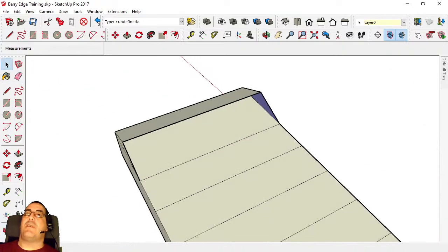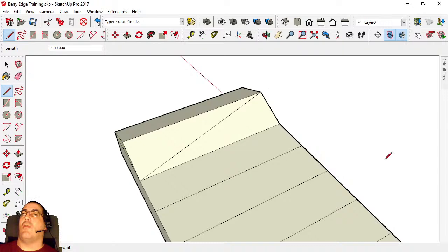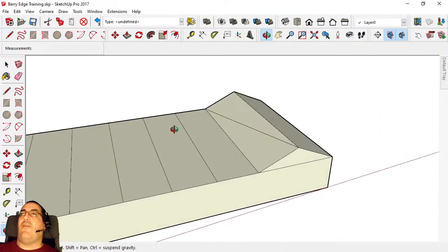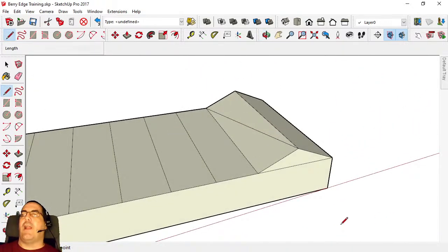And then to put that piece of roof back in, we just need to take our pencil and connect those two points back up. Now, if SketchUp can fill a hole in without requiring any weird mucking around and odd shaped triangles and tiny little fiddly work, it will do that. Yeah, you can see there that it's filled those two holes in for me automatically.